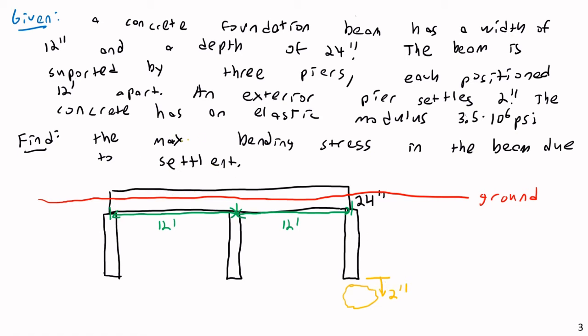Now, notice I'm asking the bending stress in the beam due to the settlement. To make this example, which is already going to be long enough, a little bit simpler, I am not asking the total amount of stress in the beam. This beam would already be supporting load above, and hopefully this wouldn't add, but it may. I'm hoping at this point you know how to linearly superpose, or simply add, stress functions together, add deflections together.